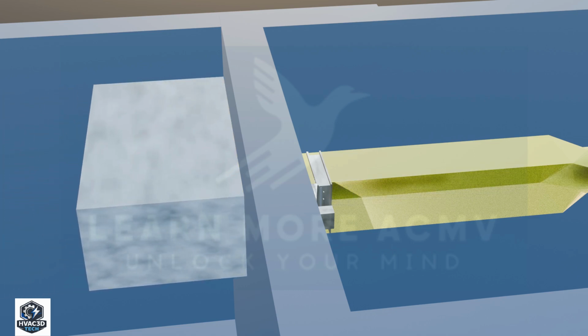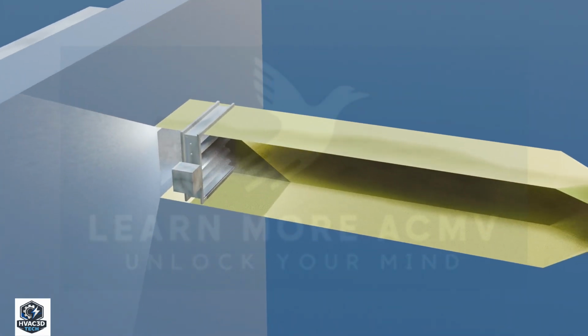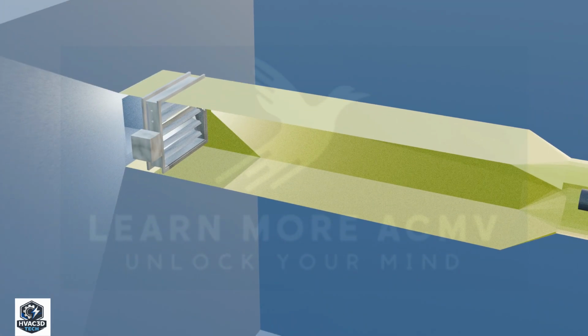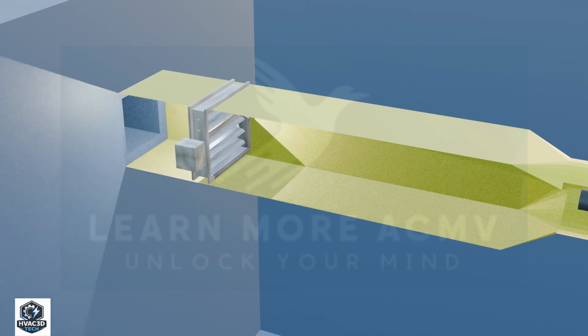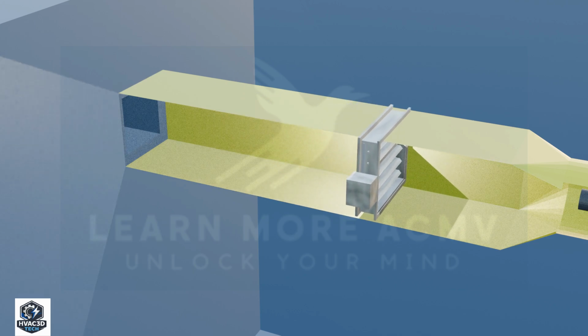In addition, proper installation of the MSFD is critical. The MSFD shall be installed as close as possible to the fire-rated wall. If site conditions do not permit installation adjacent to the wall, the section of duct between the damper and the wall shall be fire-rated to prevent fire penetration through the duct.